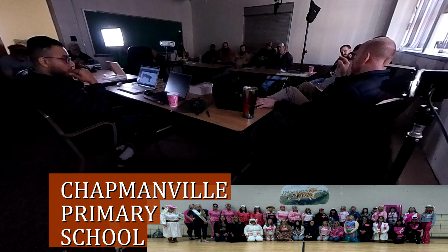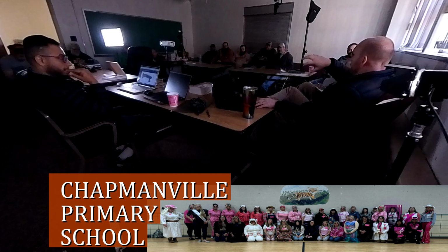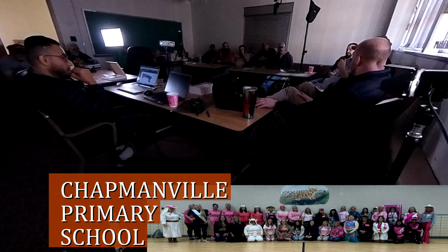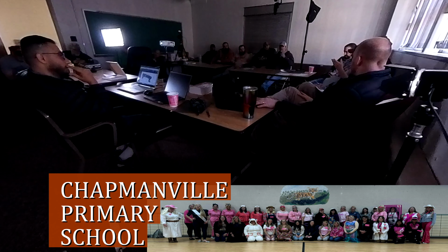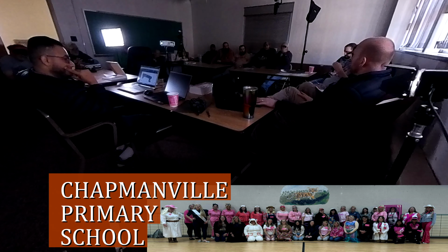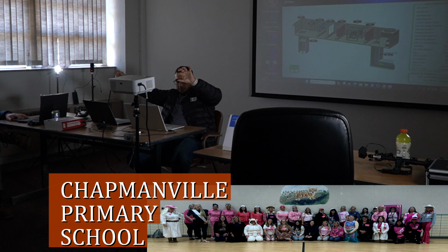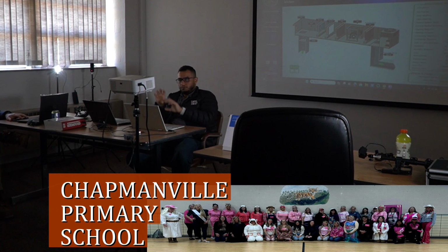So on the roof, we're tied into the Microtechs. Inside your classrooms, you've got Schneider controllers. It was just like what was there before, but you really couldn't get into that. When we do equipment training, we'll go around, I'll show you. Plus the O&M manual we provide will show you the network architecture, how it's connected, and it will tell you these are the factory BACnet, this is a Schneider controller, or whatever has been connected.